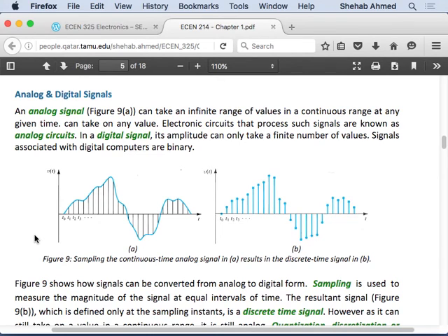So the sensor will produce a signal that is, in this case, not a pure sinusoid. It will have a component at the frequency of the visible light, and a component at the frequency of laser light, for example, right? So then these two components, you're going to be passing them through an amplifier. This amplifier circuit, we are going to design it in the frequency domain. So we will kill any signal that we do not want to see by designing it properly in the frequency domain. Okay? So we will have to deal with that in the analog domain.